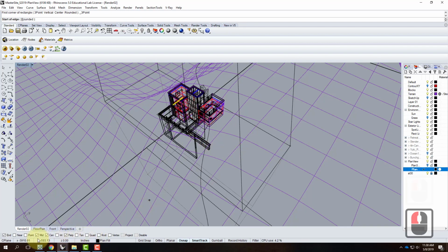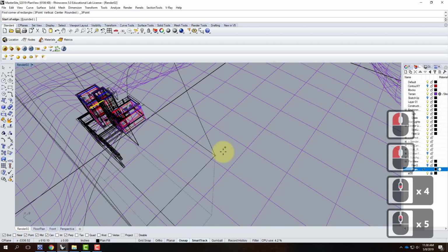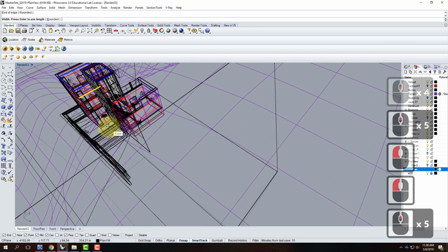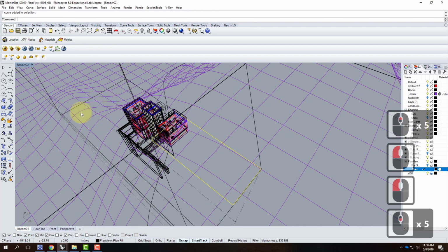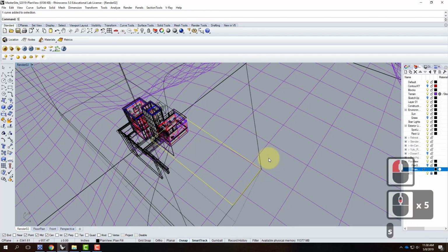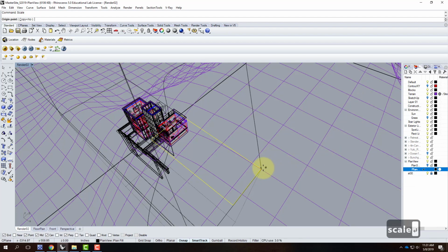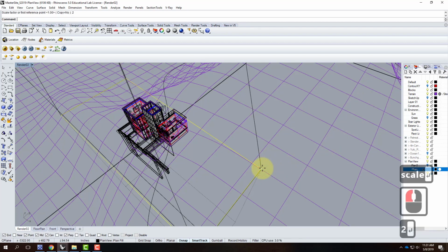I'm going to turn on my point snap. There it is. And there's my first 2 points, and there's my last point right there. That rectangle is 1/4 of the overall view. I can then scale it from this upper corner by 2 to get the whole size of the view.